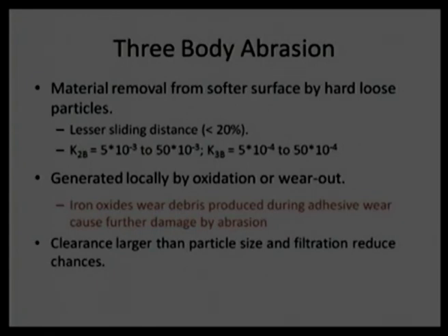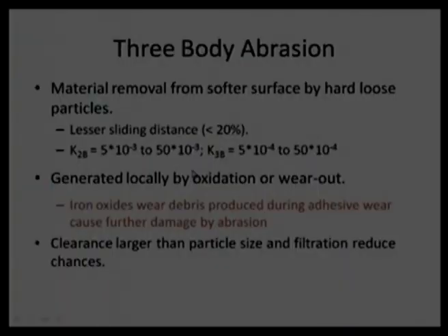Again, it is an approximation, not an absolute value, not 100%, but chances are that wear rate will decrease significantly, maybe say one order of magnitude. The reason being, particles are rolling more, causing lesser damage to the surface. But again, that rolling ratio will depend on the shape of the particle. If the particle is spherical, or has an irregular or diamond-like shape, it will cause more or less scratching. Depending on the shape of the particle, we can find out whether wear rate is on the lower or higher side.